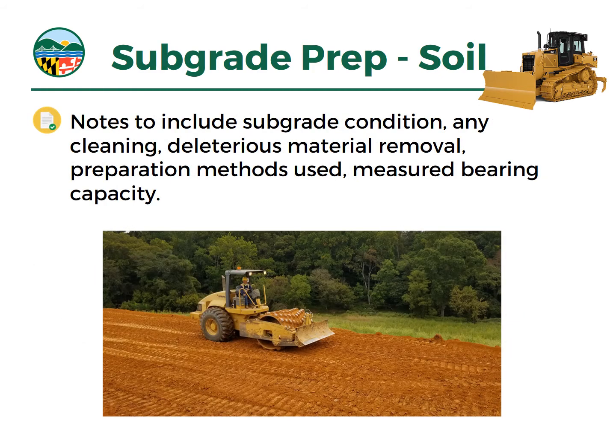And of course, as you're inspecting it, please note the subgrade condition, any cleaning that had to be done, removal of poor quality material, and any of the measurements taken or preparation.